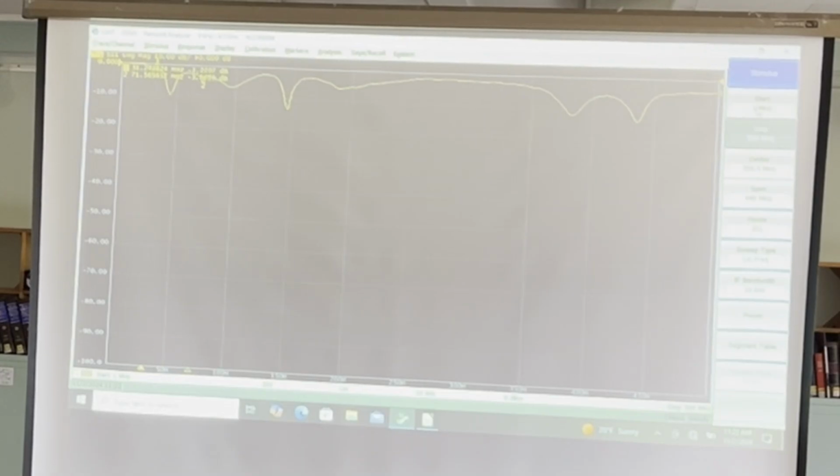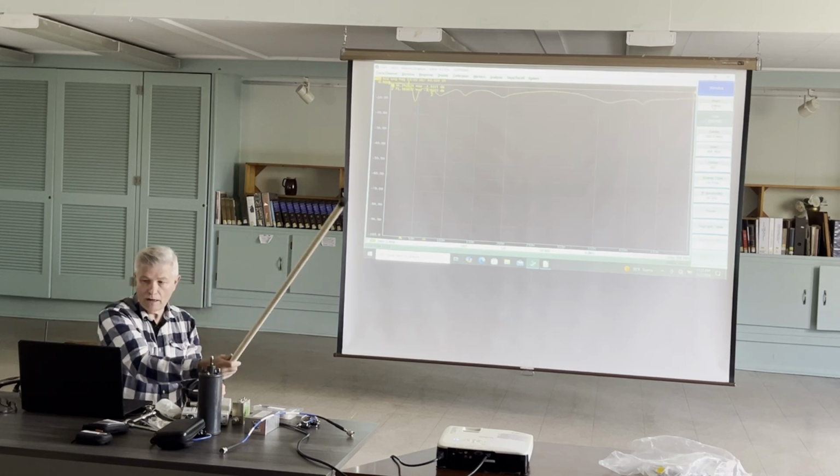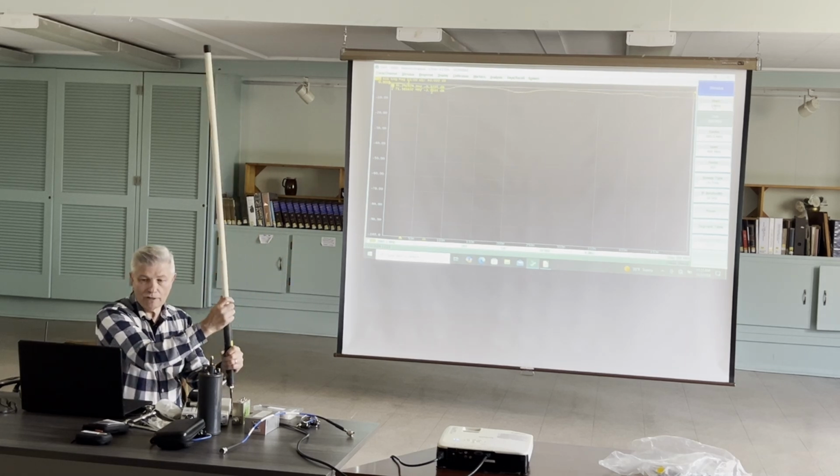Look at that, this looks like it's about 149 or 148 megahertz, but there's also another resonance point up in the 400, which is probably a third harmonic, right? 300, and it's not quite 450, but then that's not quite 150. So there you go. Again, you can see the influence of nearby objects on your antenna performance.